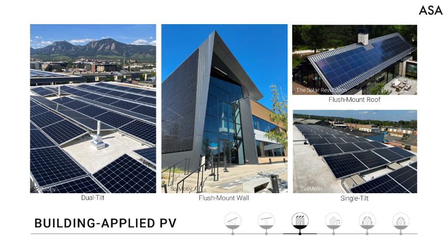As a point of reference, average added dead load of a mechanically attached system is approximately 4 pounds per square foot, compared to a ballasted system that may be greater than 10 pounds per square foot for a high wind region. A flush-mounted array is considered flush by the International Code Council when it's parallel to the mounting surface and the rear of the panel is between 2 and 10 inches from the roof or wall surface.